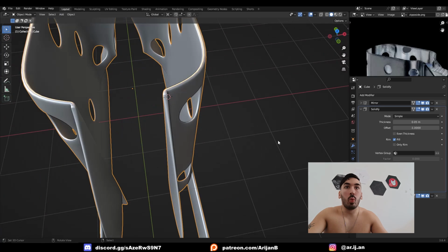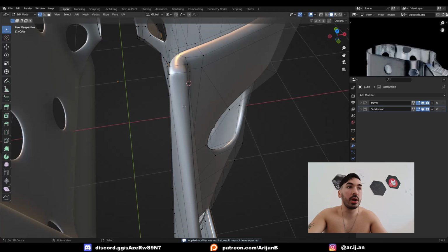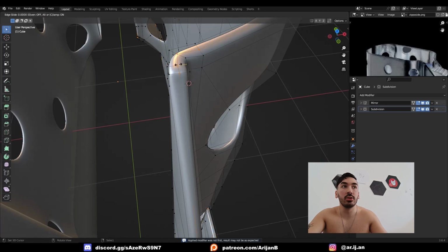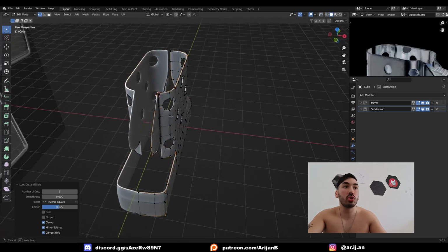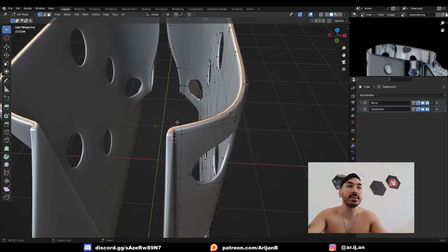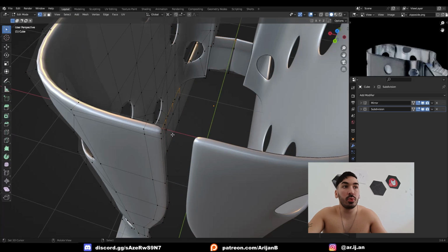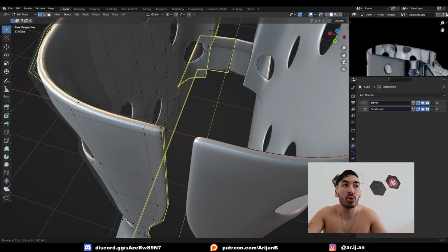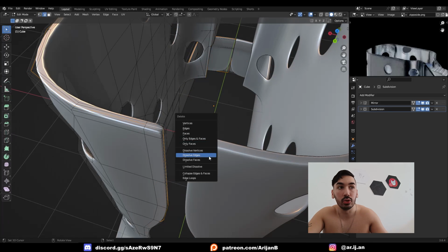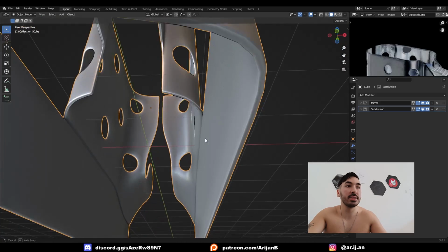little bit sharper. Once I apply my solidify modifier, I might even want to add another loop cut here that goes all the way around this object, because that's going to drastically change the way this looks. If you really want to go crazy, you can even add 2 or 3 loop cuts to this and remove the middle loop cut. This way you have a practically perfect shape.